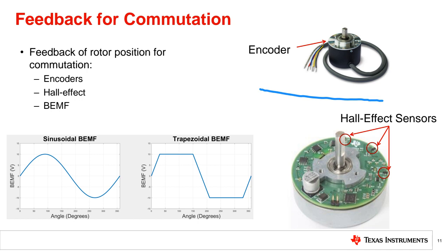For example, if your BLDC motor operates at a rated 3000 revolutions per minute, in a sensorless motor control application you cannot control it below 1 over 10 of rated speed, so under 300 revolutions per minute you cannot control it using a sensorless technique.